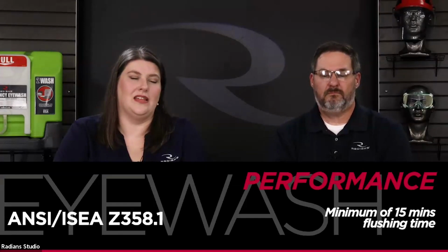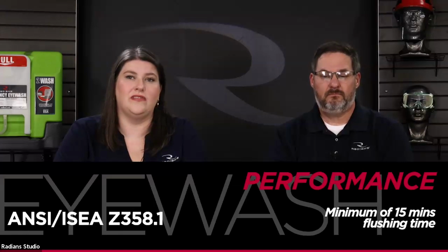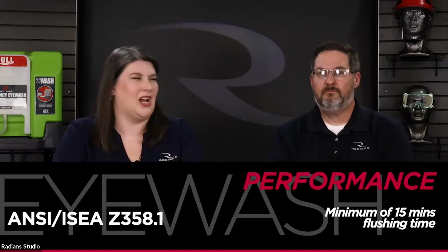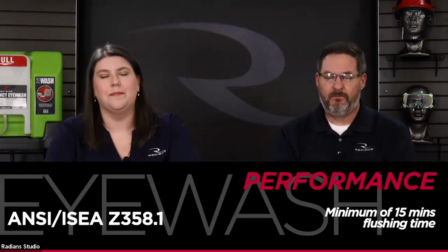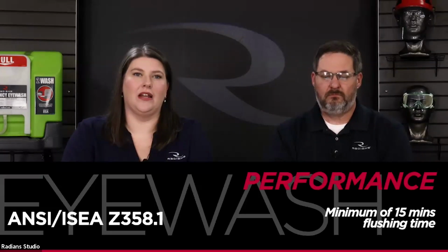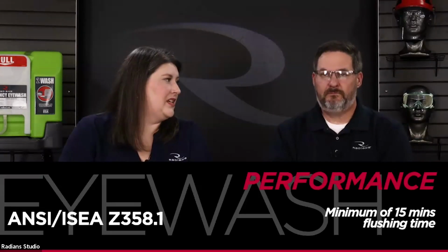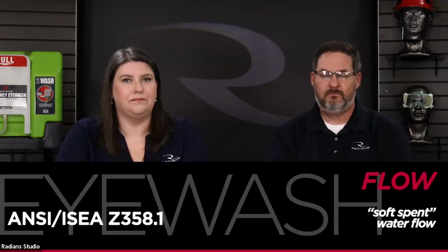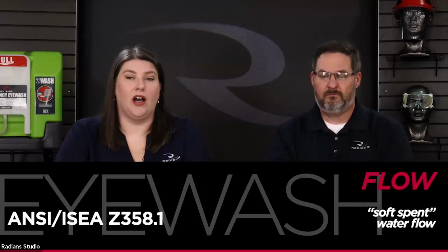For any emergency eye wash device, you're going to want to look for a device that is rated to ANSI ISEA Z358.1. That standard first of all calls out the performance requirements. It requires that any gravity-fed, self-contained portable unit, all those terms are kind of interchangeable in the market, have a minimum of 15 minutes of flushing time. So the water coming out of those devices is going to continue to flow for at least 15 minutes to properly flush your eye. The flow also must be soft